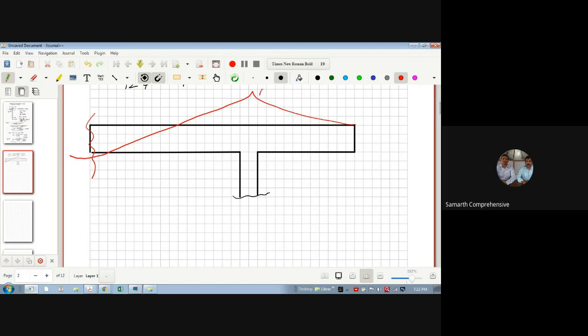And whenever I say bending moment, all of you know that bending moment is nothing but a tension. So there has to be some bar which will take the tension here. So I will provide this bar, but the tension is not till this point. You say that bending moment is still there on the top of this beam. So the tension is still behind the bar, behind this cantilever beam. So I need to develop this bar back into the beam. Okay, so I need to develop this bar till the development length.